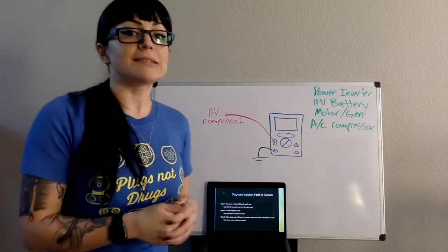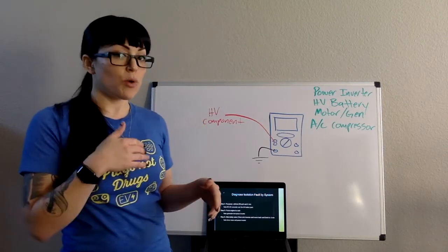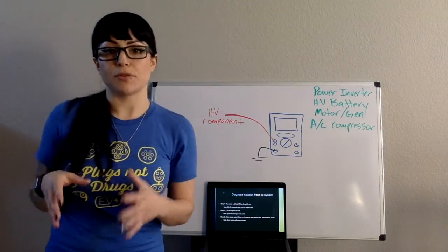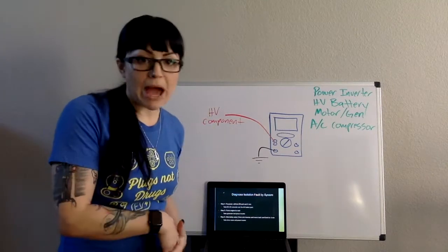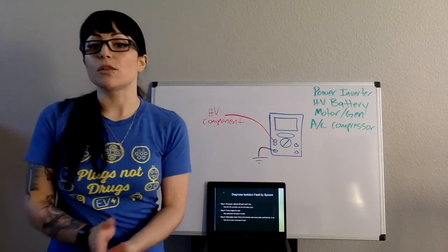So if during this time we get an isolation fault code while we're in drive or in reverse, well, now we've isolated it down to either the drive motor or the power inverter. So then now we know, okay, it's time to go test those components.